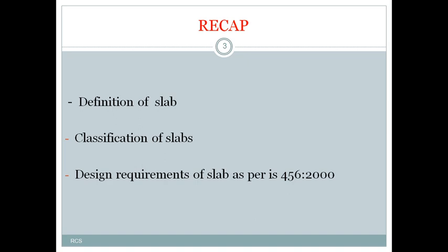By using these two conditions, we can calculate the effective span of the simply supported slab, and we consider the minimum of these two values as the effective span.